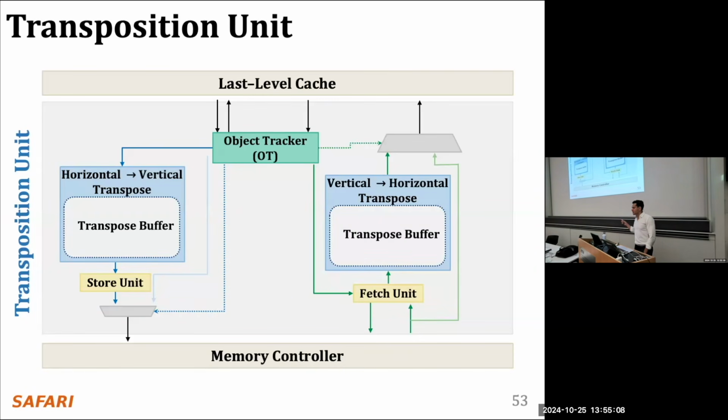So I was not clear because I didn't give the sequence for the ripple carry adder. But basically, since I know that that bit is going to be used both for carry and for the sum, once I compute, I also copy to a temporary row so that I can use it later and don't destroy the bit for the sum. Essentially, you move A and B to the computing area twice. We move B once, we move A twice because of how the circuitry is designed. But B is only moved once, A needs to be moved twice.